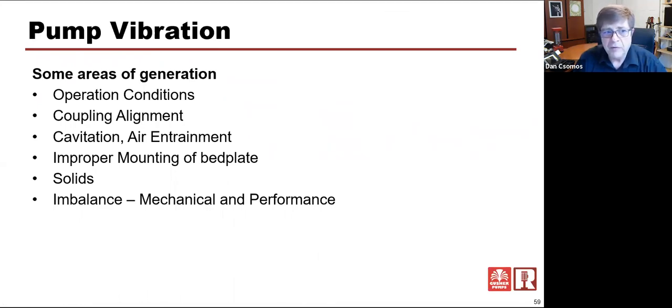Why does a pump vibrate? Bad operating conditions. We've talked about both sides of the curve, left and right. Are we too far towards deadhead? Are we too far out on the curve? I guess if I'm looking at it from your perspective, it would be the other way around, too far left or right. I'm hopelessly right-handed, by the way.